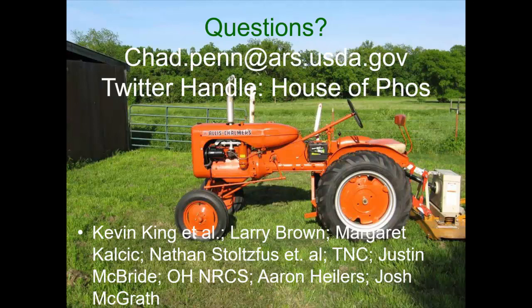What happens if your media goes anoxic, the redox? Okay, so that is an issue for the iron. Can you repeat the question? Yeah, sorry. The question is, what happens if the media goes anoxic? That is an issue for the iron oxide-rich media. And that is why I've never built a field structure with iron oxide-rich media that flows from the bottom up. From the top down, it's free draining in between events. You've got oxygen. But if we build it to flow from the bottom up, then in between events, it's going to be saturated in water. It can possibly go anaerobic.